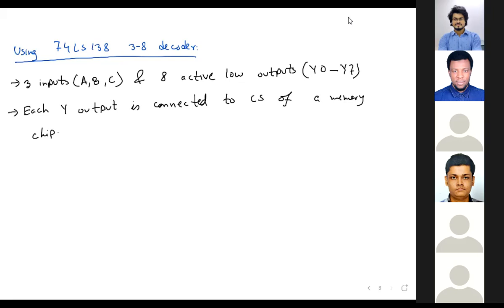If you see the pin configuration, you will see that we have got 4 ports, right? Port 0, port 1, port 2, and port 3. Port 1 is simply port 1. Nothing is written beside it. But when we go for port 0, beside port 0, there are a few things written like AD0, AD1, and those things. Beside port 2, there are a few things written as A15, A14, and all these things. That means your port 2 will always be your address pins in this particular example.